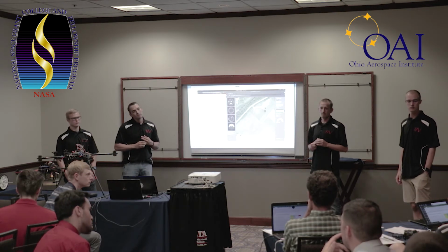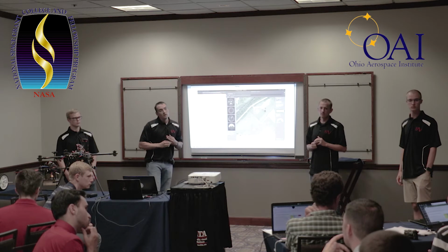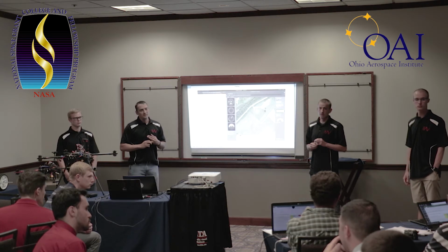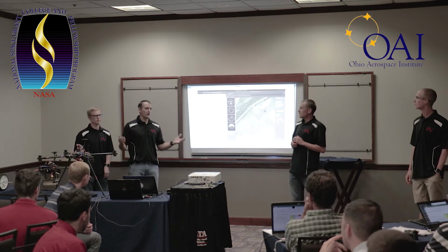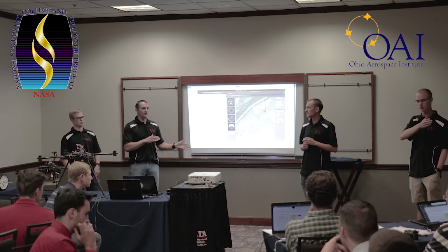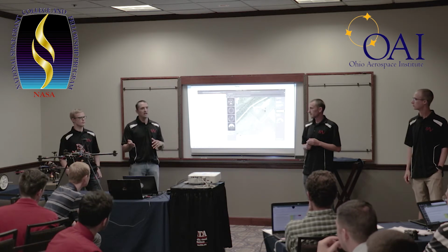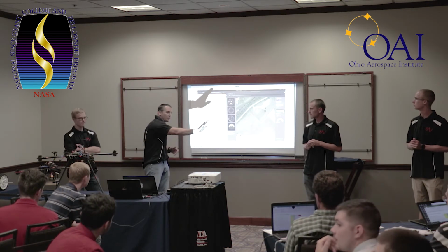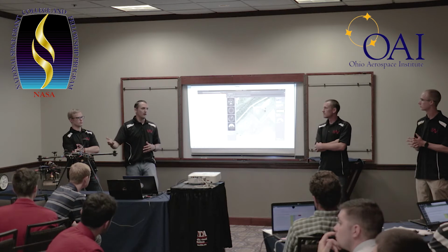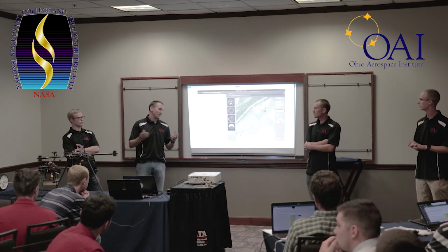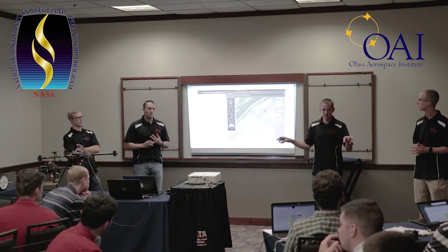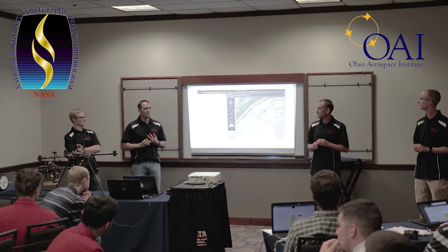Now, you came up with this 10 meters per second speed. Is that kind of the best speed for going the most distance? Yes. So that's the optimal speed for which we can travel the furthest distance. In this particular competition, where we're turning every sixth of a mile, with this particular set of maneuvering, that happens to be our best speed, accounting for a hard pitch and then a transition back, and obviously the subsequent altitude deviations that you get through the Pixhawk and through just those kind of multi-coupling controllers, that just happen to be through our testing the best. Yeah, it sounds like a nice round number, but we actually tested a bunch of numbers, around every number between 6 and 12.